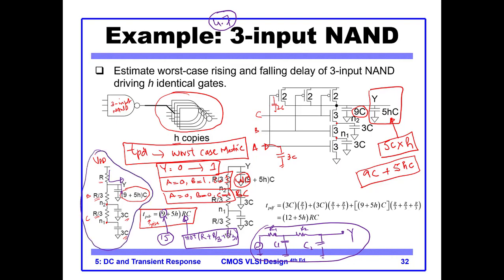Here the output is not shared among all the capacitors, but only the output is taken from one node. In that case, we have to count all the capacitors at every node, but the resistances, because they are not on the shared path, will not be considered. This is very important to understand.